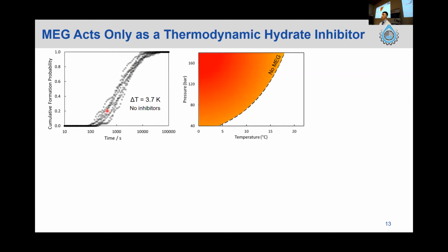And if I draw a straight line at P equals 0.05, that is equivalent to 95% confidence. So we are 95% confident that we can operate the system without any probability of forming hydrate for an X amount of time. And that X amount of time in an uninhibited system is about 5 minutes. Once again, 5 minutes means nothing to the industry.